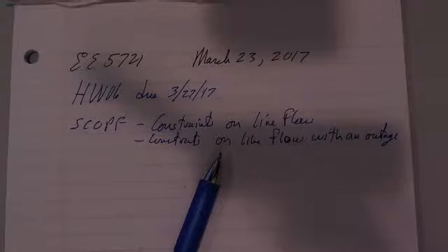And what we're doing with the SCOPF is pre-dispatching. We're dispatching the system, given the load that it has and the generation units that are committed. Then I can schedule the generation and know that any single outage will not result in an overload.